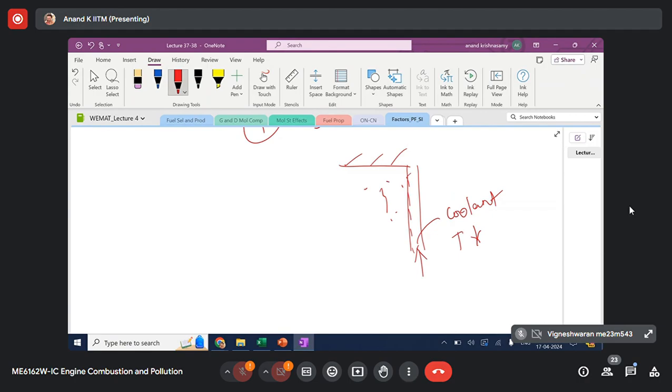Temperature will be lower, sir. The evaporation of fuel will be very low. So when you have coolant circulated at lower temperature, the wall temperature is also low. When wall temperature is low, there are a sequence of important processes that will take place because of the lower wall temperature. There are several effects here. One of the effects is that you can expect a high crevice flow.